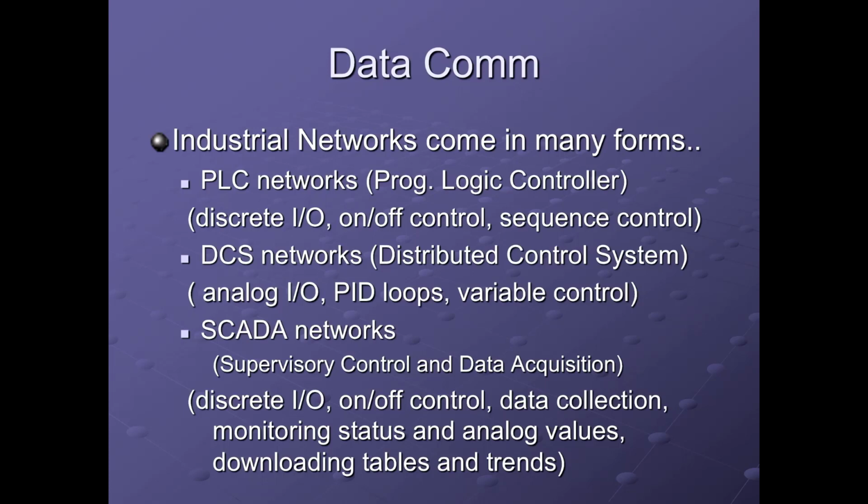So when it comes to the SCADA network, what is really important to understand, aside from what we talked about in terms of DCS, is that one thing that really separates it from DCS is that it's only a few points that are being monitored and controlled, but it's a wide area network. A SCADA network is distributed over a large geographical area, so it's pulling in a few points, not a lot of points, from remote locations over a large area and displaying them to a central master.